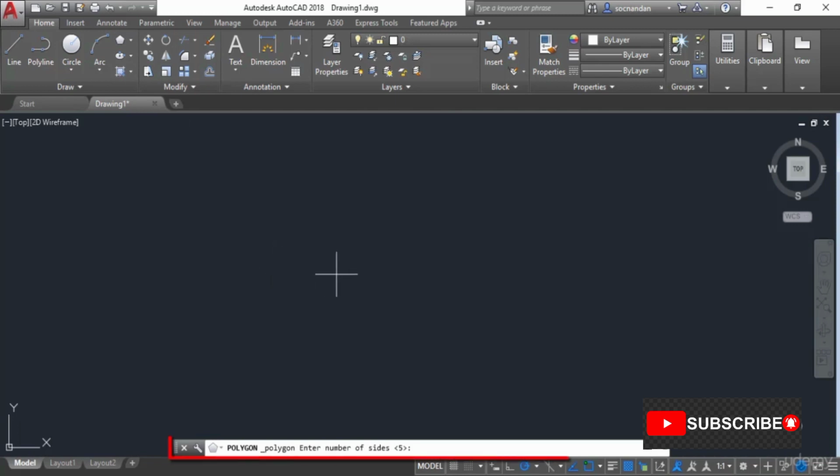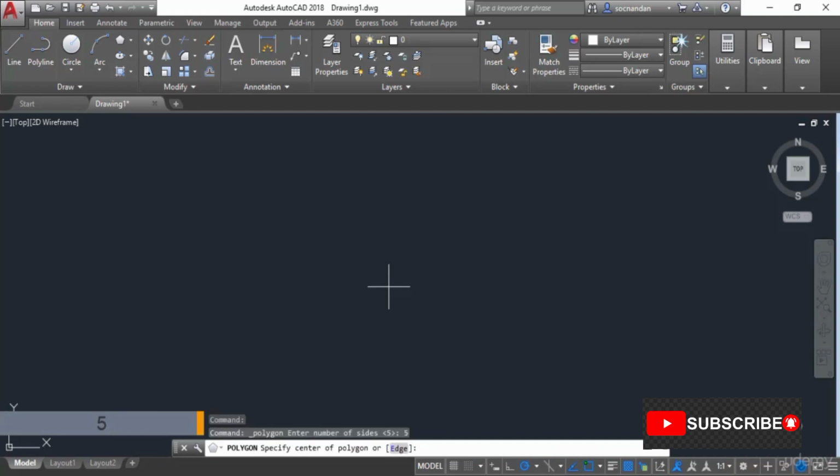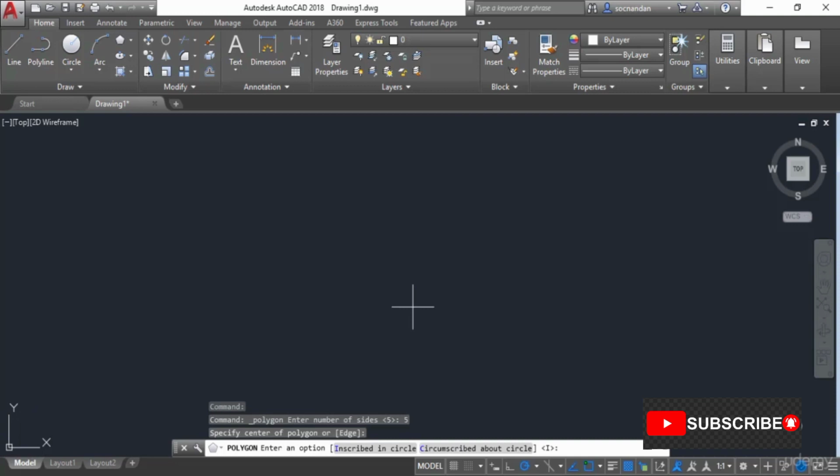Now after starting the polygon tool, you'll see on the command line we have an option which says we need to enter number of sides. So you can enter any value between 3 and 1024. So let's enter 5 and press enter. So we are making a pentagon now, and now you need to specify the center of polygon. So click anywhere in the drawing area to specify the center, and now look at the command line.